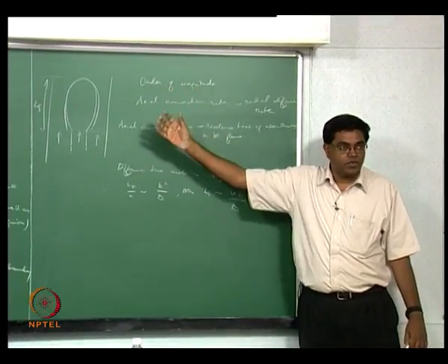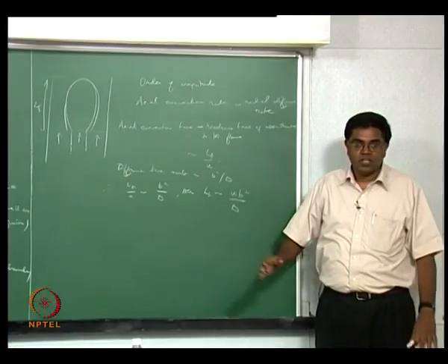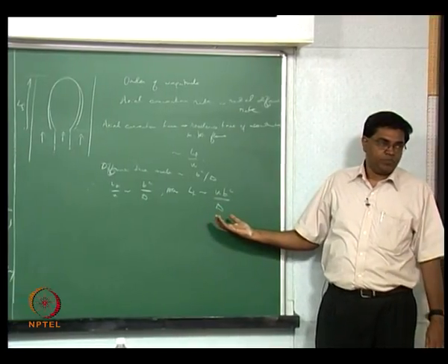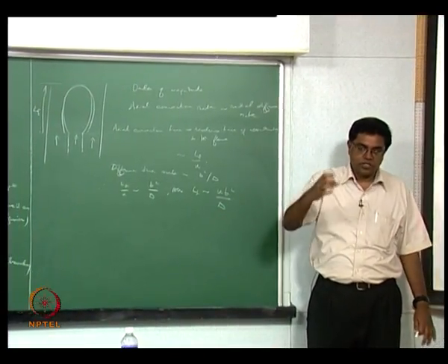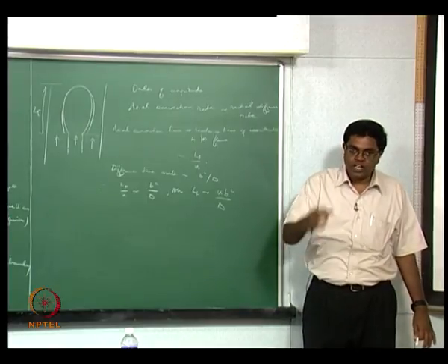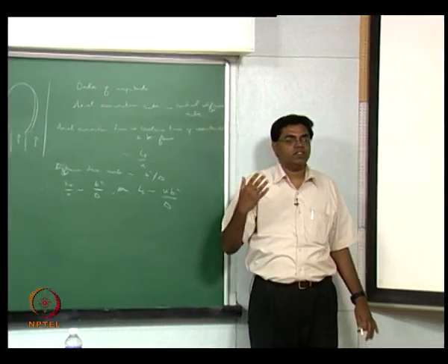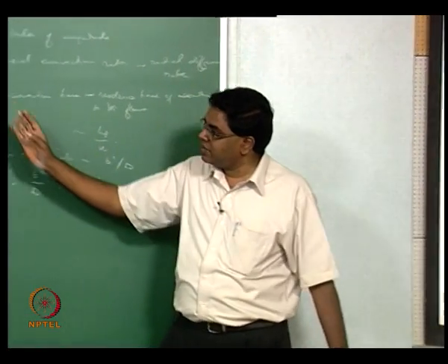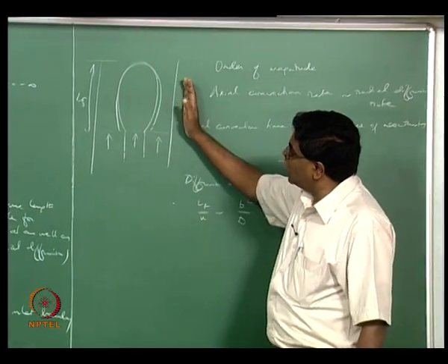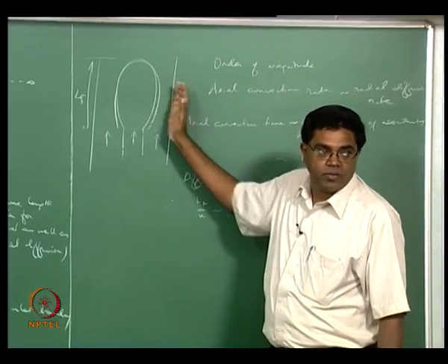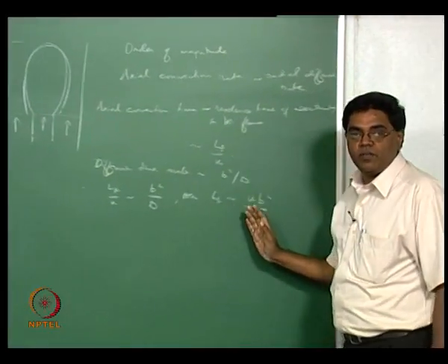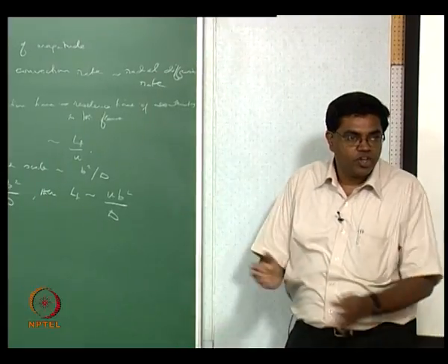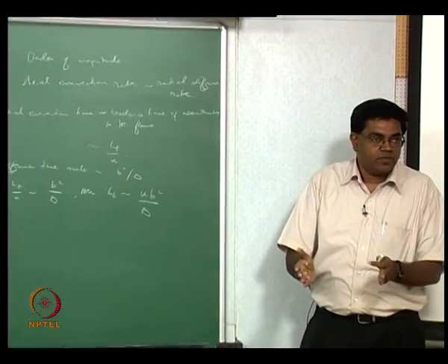not just for the Burke-Schumann problem or the Burke-Schumann geometry where you have coaxial ducts, but even for jet flames. So if you have a fuel jet that's coming out of a pipe of certain radius r or diameter d, you could still say, don't worry about the fact that you have to use the outer duct diameter. The order is not going to be significantly different if you use the inner duct diameter, alright.